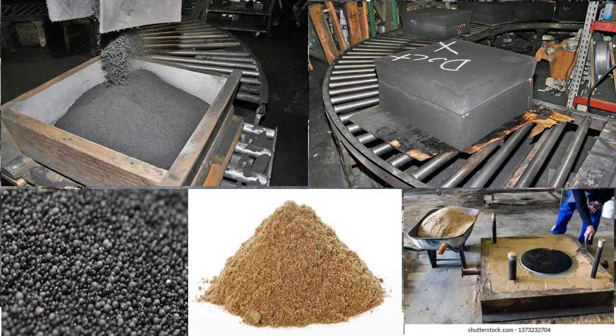A typical foundry sand is a mixture of fresh and recycled sand, which contains 90% silica, 3% water, and 7% clay, where the clay is considered as a binder for the sand particles. The grain size and the grain shapes are very important as they define the surface quality of the casting, and they determine mold parameters such as strength and permeability.